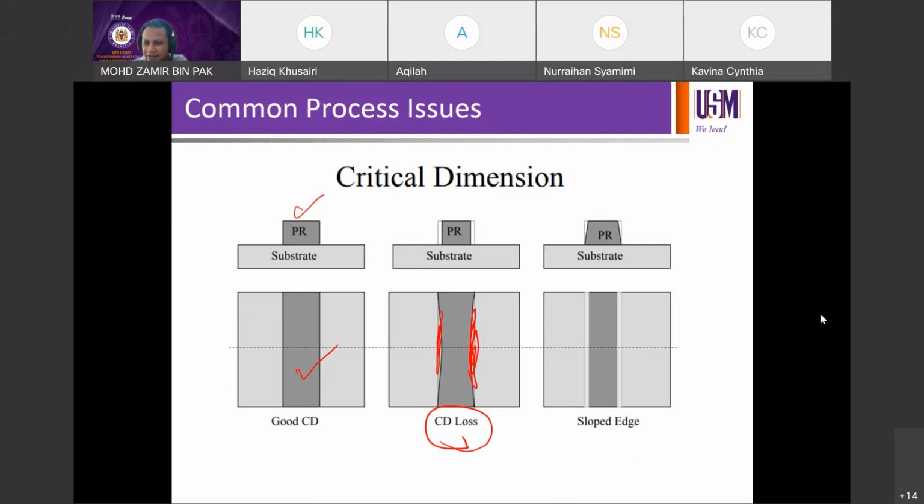Still thinking. All right. So assume this is our operation meeting. You're updating your CEO. Amiro is the backup process engineer for this line. You're printing lines, and your CD is drifting on the high side. You're supposed to get 100 nanometer, and you're now getting 125 nanometer. Your problem is due to the scanner dose. What do you want to do?